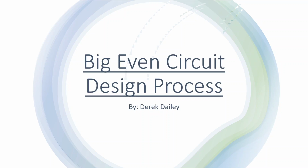What is this circuit called big even? Well, it accepts the unsigned binary output from a 10-digit keypad and will output a high value only if the input is an even number larger than 3. Now that we know this basic information, let's get right into the design process.